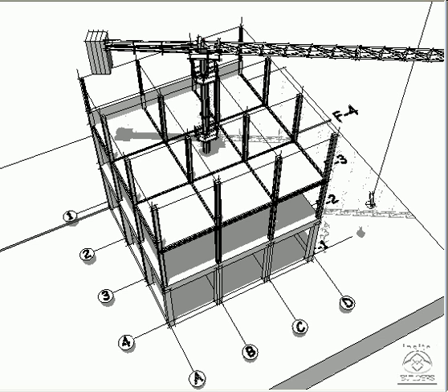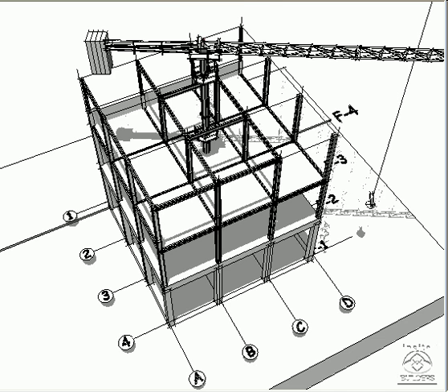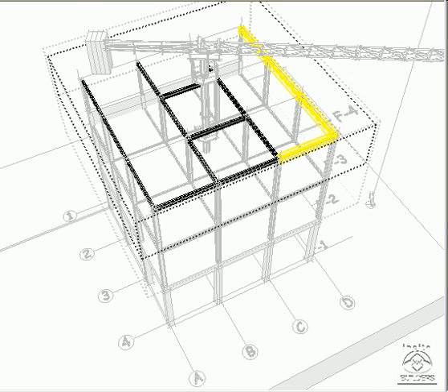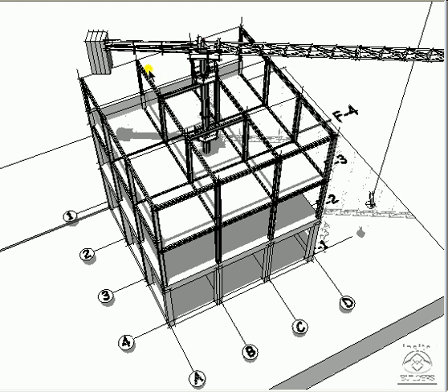The beams are also placed in a way that makes it easy to lift them from the shakeout area. Since the ironworkers are placing just beams, they can stay in the upper levels of the steel structure, moving out from the core, then off to the perimeters in both directions.